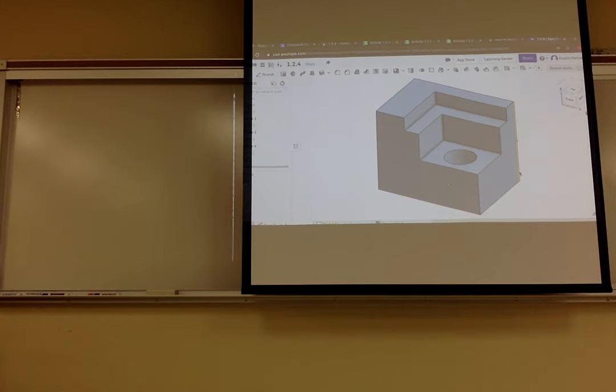Good. Remember the trick. Click on that part. Right click. Click on that one. Right click. Create a drawing above that. Then click the 4 views. It'll do 4. It'll say, how exactly would I draw the L?